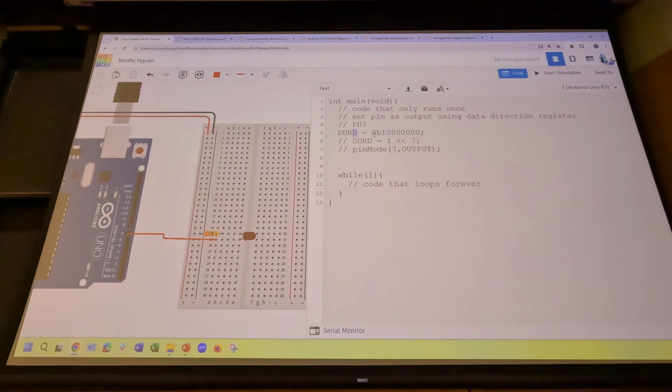Gotcha. And the position of the 1 would be from counting the number of digits from right to left, to the 5th position? Yeah, PB0 is there, just remember to start counting at 0, right? PB1 is there, PB2 is there, PB3, PB4, PB5. And the 0B in the front is just standard? Yeah, that's just standard to indicate that this is binary as opposed to a decimal number.